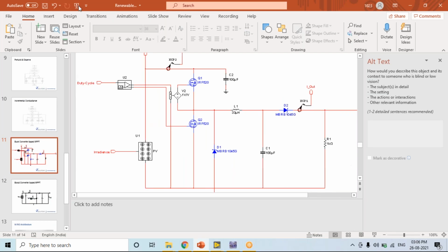So here we are going to create a buck converter. Values have already been selected for the purpose. For the calculation of values, we can refer to a proper reference tool; there are plenty of tools available. To change the values of your inductance and capacitance plays a very dominant role. Apart from that, the MOSFET, which is based mostly on output voltage and output current, and also input voltage and input current. Both of them should be considered.